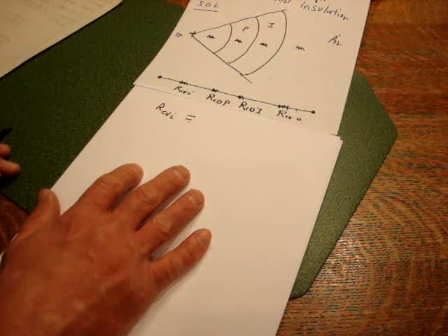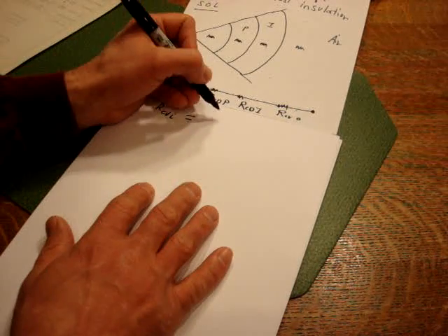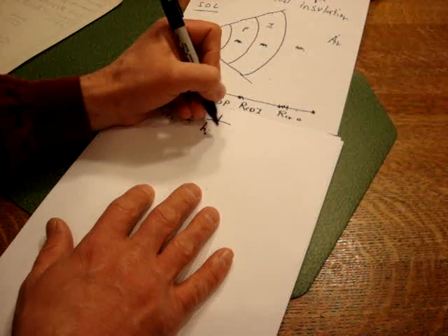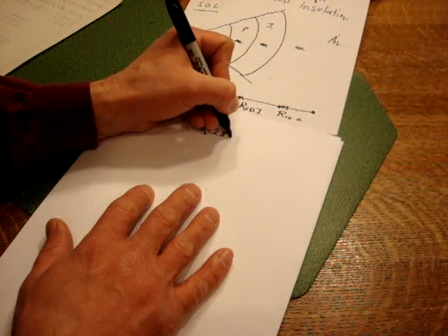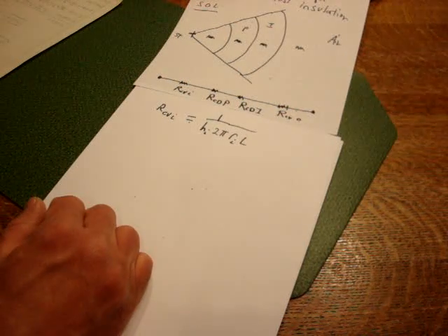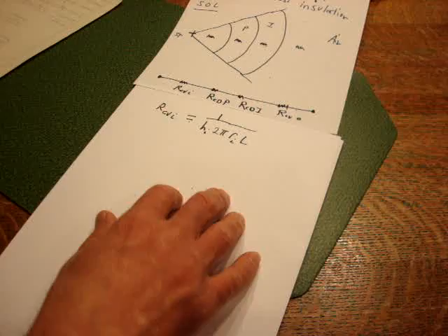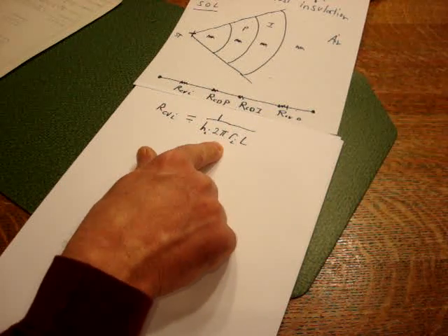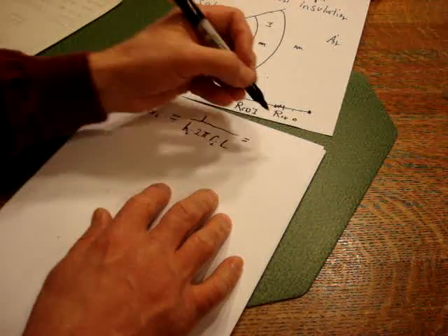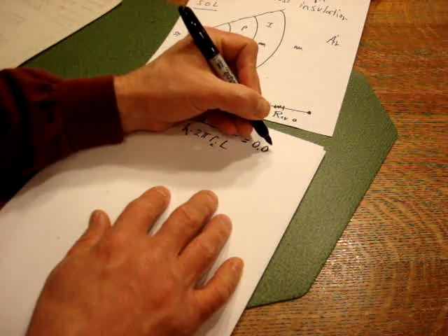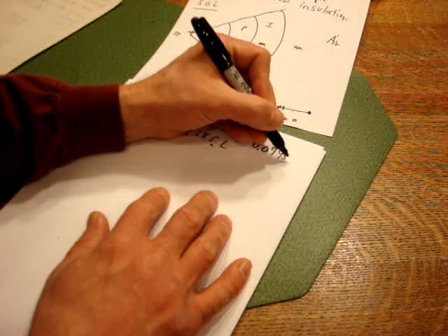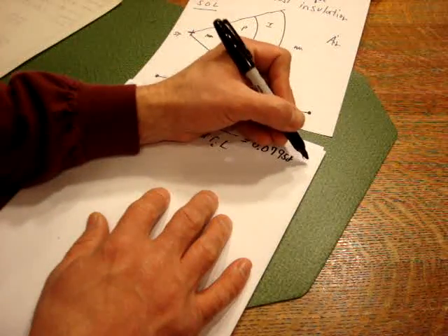1 over H on the inside, A on the inside. So what we have here is 1 over H on the inside, the area on the inside, which is 2 pi Ri, times the length L, which of course is going to be 1 meter. All this stuff here is given in the problem. If you put the numbers in there, crunch it out, what you will see is that the value is 0.07958. And that is Celsius per watts.